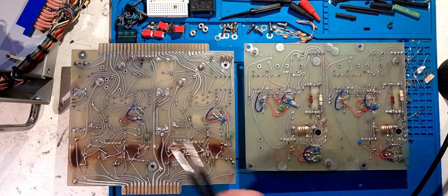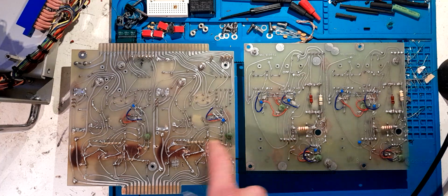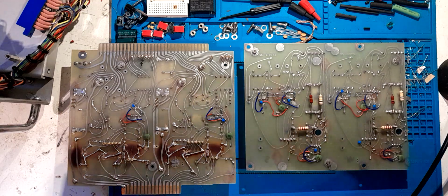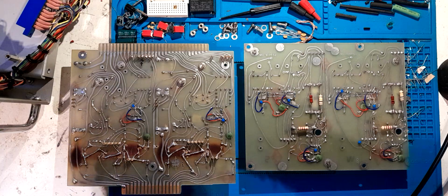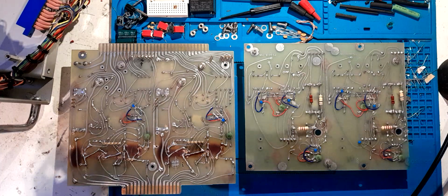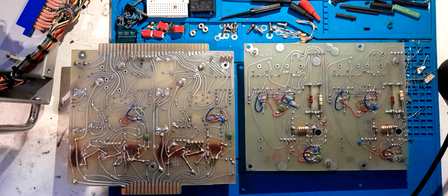But anyway, this is what I'm thinking. And obviously I'm going to remove the 10 nanofarads again. Look, I genuinely think that these are the bypass caps they use for the op amps. That's what I think they're for. And like I said earlier on, that was just the old way of doing it. I'm going with 0.1s. I don't have much more to say on that, so without further ado, I'm going to install these, then I'm going to put the boards together, then we're going to start scoping stuff out. We'll see what we can do.